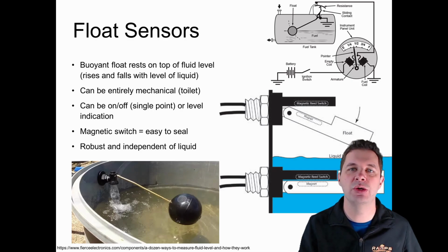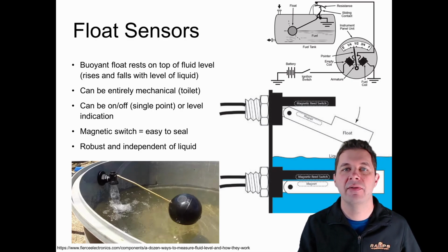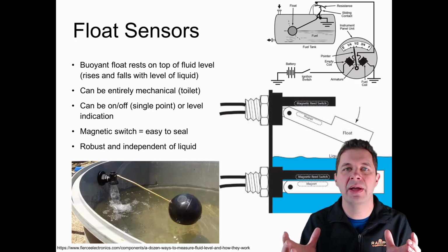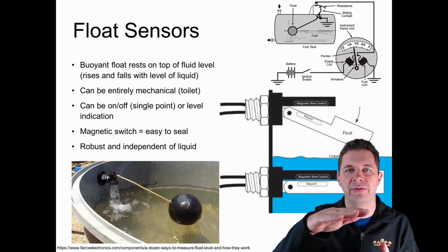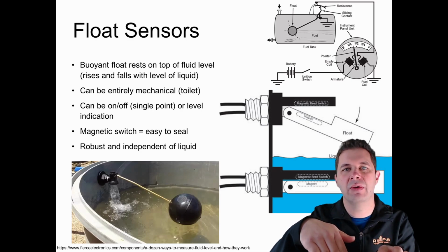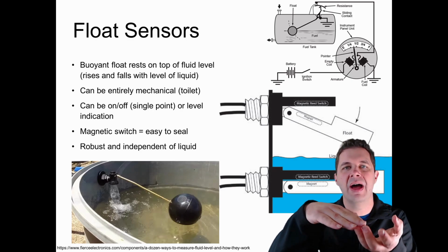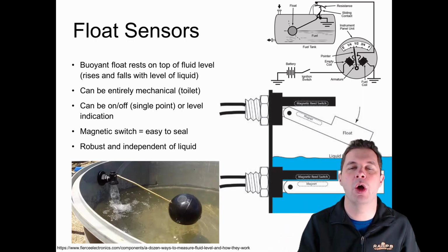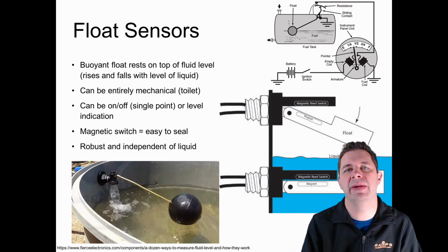Likewise, these are sometimes used on farms and things when farmers want to keep some water troughs filled up, and if the level gets too low, the float sensor opens, water can run in and fill it up, and as the level rises, it'll cut off the water flow and stop it there so the troughs won't overflow. These float sensors can also be used electrically.